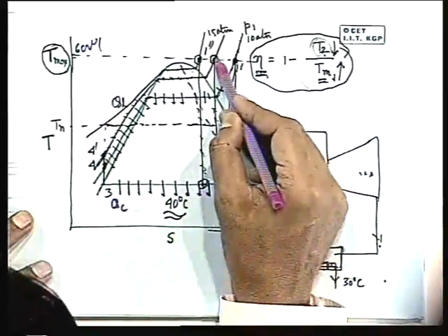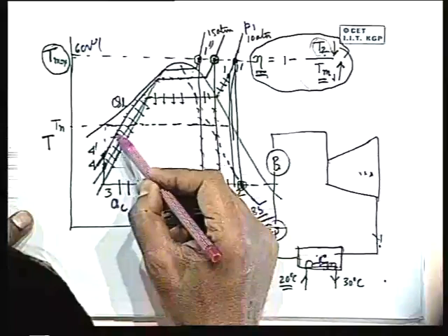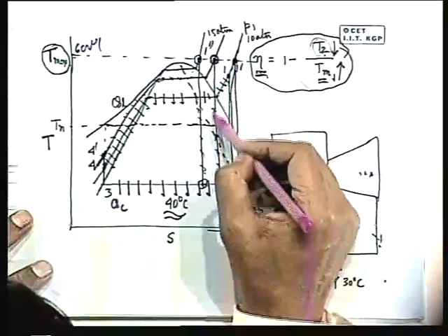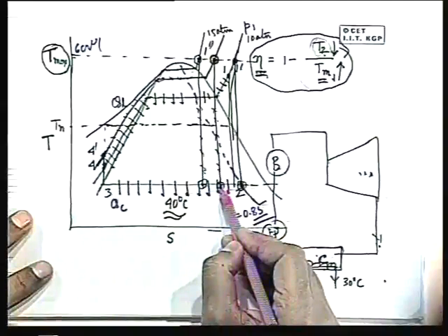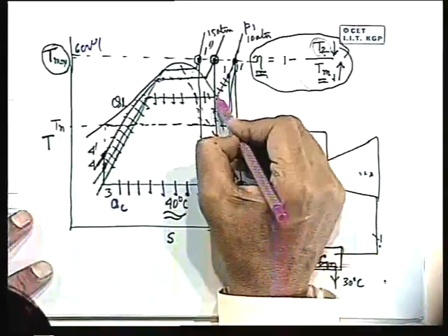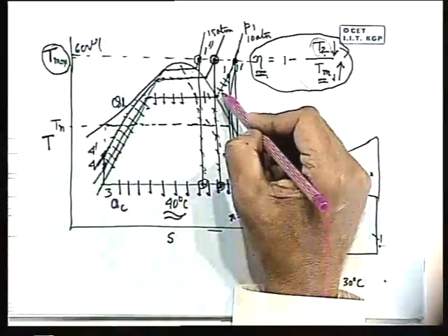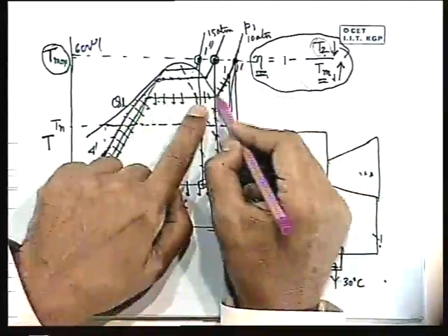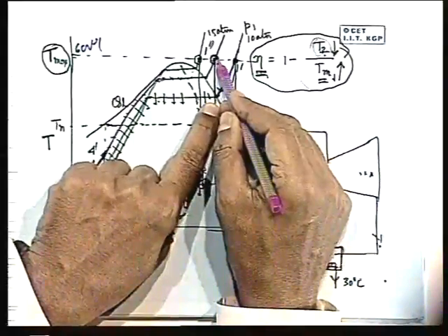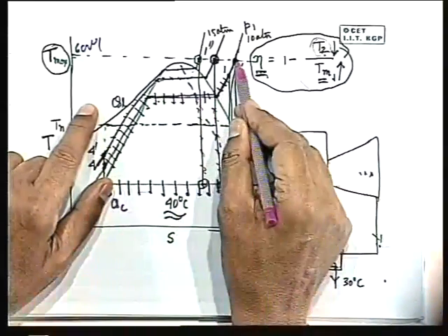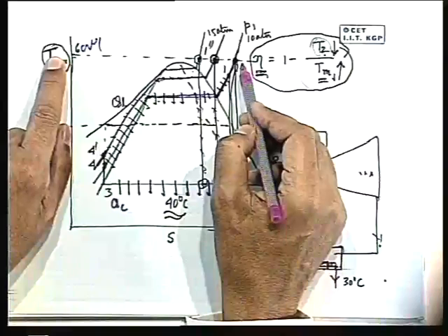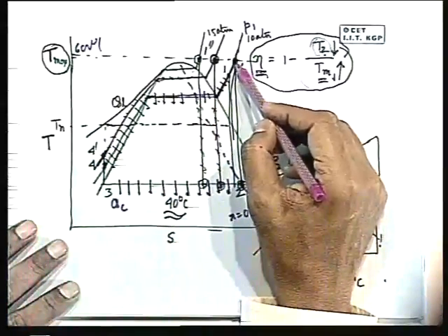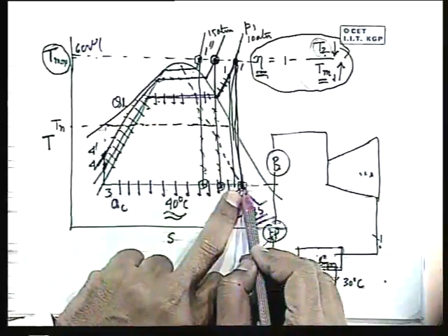But I can do so. How? Now, if we start with this point, that means if we increase the boiler pressure, heat the water at higher pressure, evaporate it or boil it, then again superheat it and start with this point even, but don't go all the way from this point to the condenser pressure. Instead, you expand up to some point here, for example. Then you take this steam to a heat exchanger for heating it, which is known as reheating. That again heats the steam at that constant, reduced pressure. That means the first expansion takes place from the initial pressure, not to the condenser pressure, but to an intermediate pressure. Let this be the intermediate pressure. Then heat it again to the initial temperature. Sometimes it is not heated to the initial temperature, but we will consider in an ideal case it is heated to the initial temperature, and then if we expand it, we get the same point here.